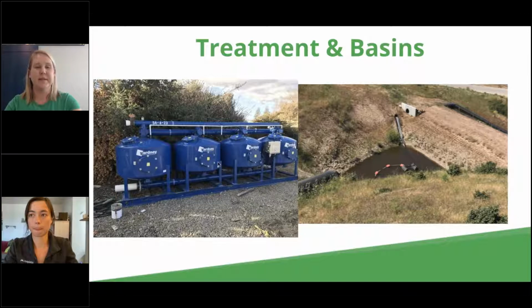If you have a treatment system at your site, you want to make sure you're following the vendor's recommended schedule for maintaining the chemicals and the media that is in that treatment system. You don't want to be surprised by a high value in your sample results because you forgot to maintain your treatment system.